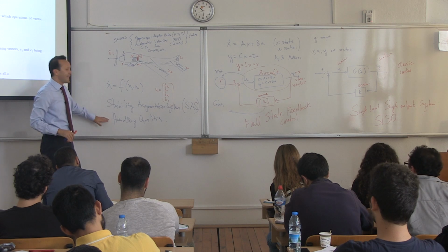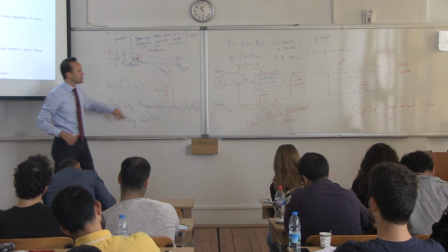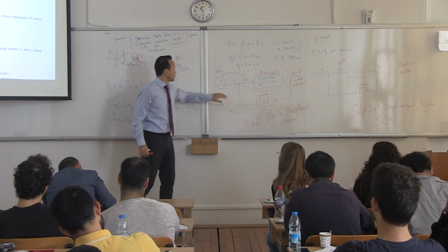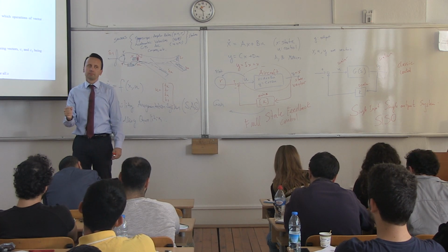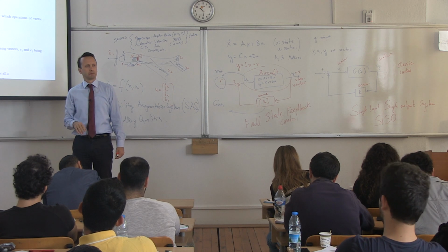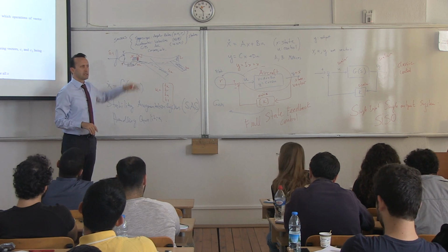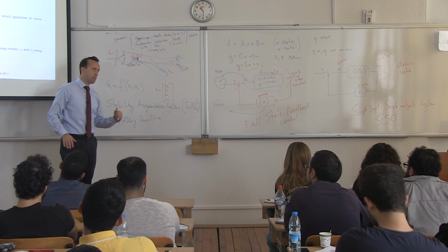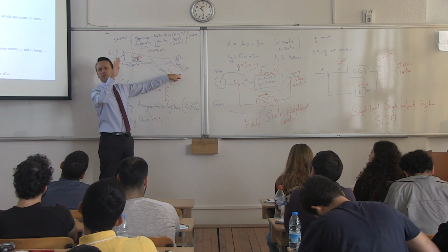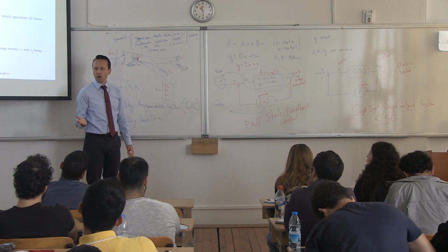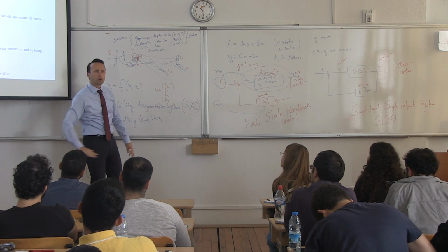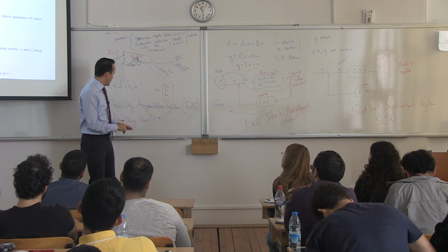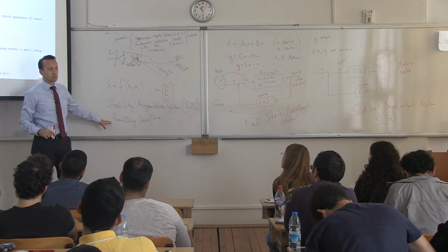We improve the handling qualities of airplanes using controllers. Using just that. So the pilot will give a pitch up. Maybe the airplane doesn't want to pitch up. So this computer here says, oh, that's not enough. Let's give more input over here so the airplane goes really up. But the pilot doesn't even know. He just did this, and the elevator is doing a lot of work to give you that pitch up. So that would be increasing the handling qualities. Okay.